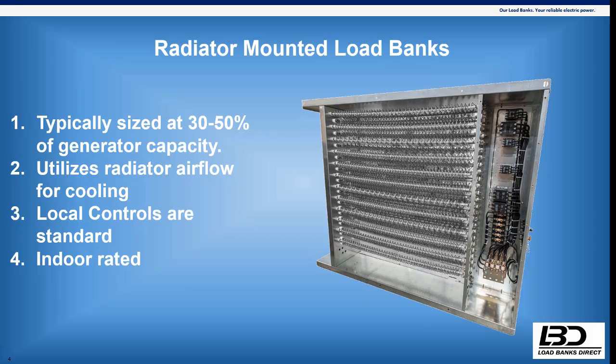Hey Eric, where's the cooling fan on these resistors? Oh, they're not self-cooled. They are being cooled by the generator's fan that's blowing through the radiator. So it goes from the fan through the radiator and then to our load bank to cool all the resistors.